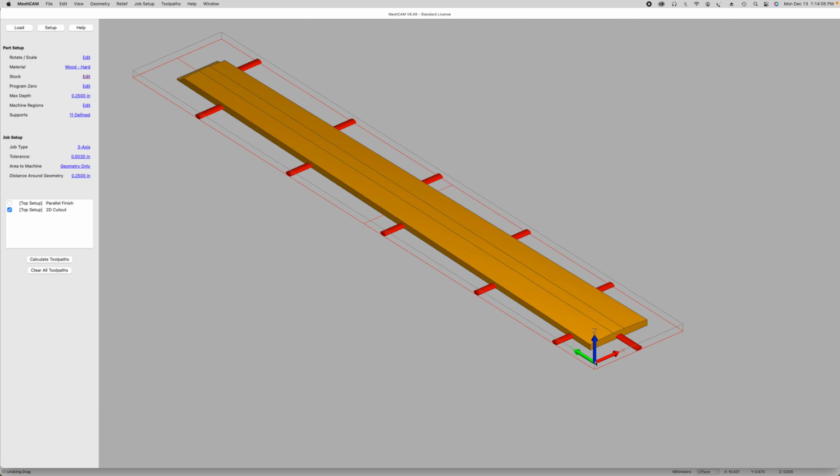Now, there are a wide variety of different carving strategies when it comes to forming a radius like this. Typically, when we are doing CNC carving operations with three-dimensional shapes, we're going to do two kinds of carves, a rough carve and then a finish pass. The rough carve hogs out most of the wood, but it leaves the surface fairly rough. The finishing pass, however, will clean that up and smooth it out and give you a nice smooth finish that requires very little sanding. However, you don't always need to do a rough cut and a finishing pass together.